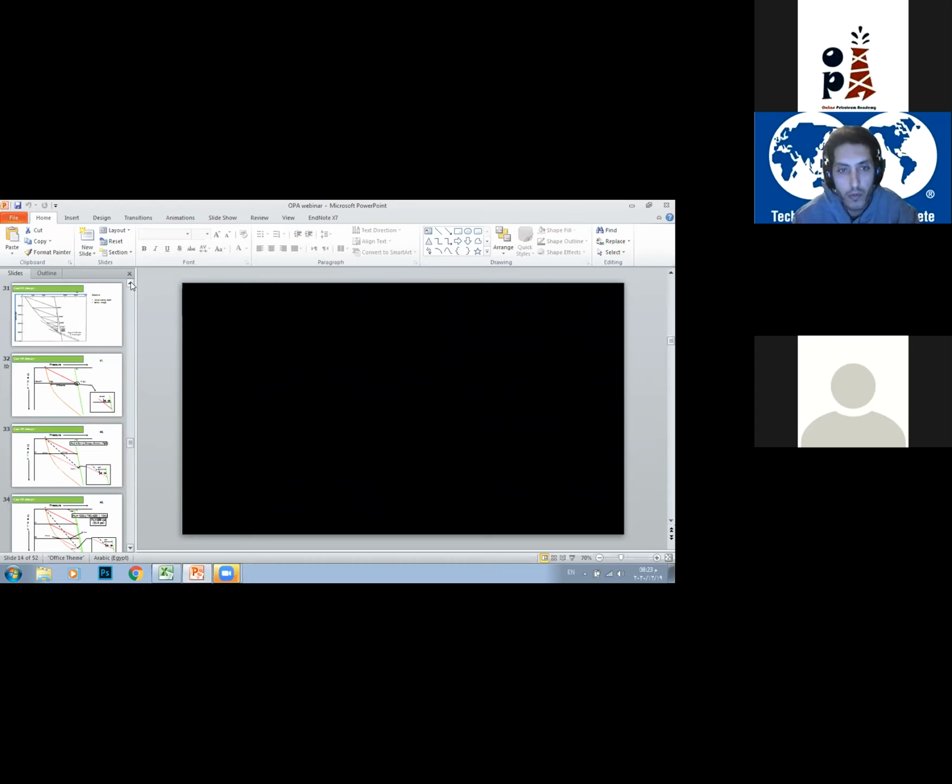So if the well is performing well, and I know from the parameters, from the temperature, from everything that this well is good, why do I have to do a gas lift survey? No, I don't. But I do it when I suspect some problem. When, for example, I'm producing from the well, then the parameters changed. The temperature is supposed to be 100, now it's 90. The well is supposed to give me 1,000 barrels, now it gives me only 600 barrels. You know, something like this.